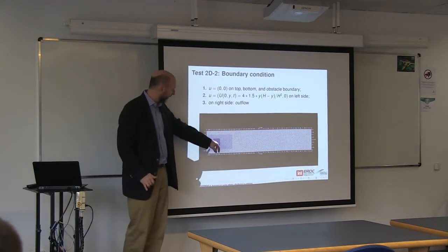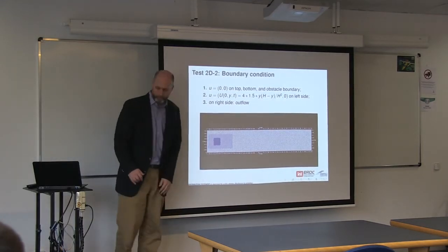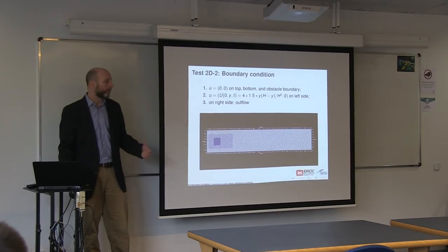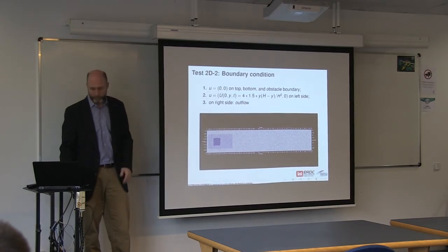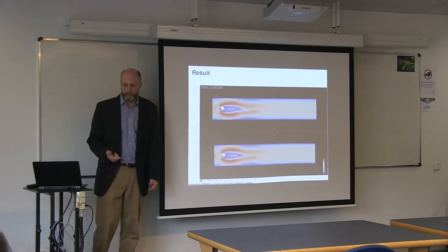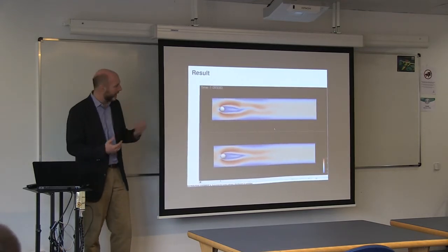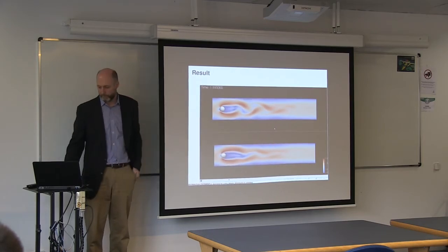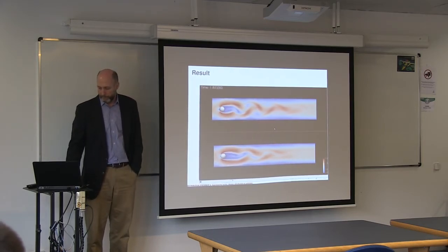And you see here, again, we have to actually do quite a bit of refinement near the solid surface that wouldn't be necessary, at least not as necessary, with a fitted boundary method. So we're paying a price for our immersed boundary method. And so this is the comparison of the two. There's really, at this point, if we do sufficient refinement, to the eyeball, you get the same types of vortex shedding properties and the same types of boundary layers.